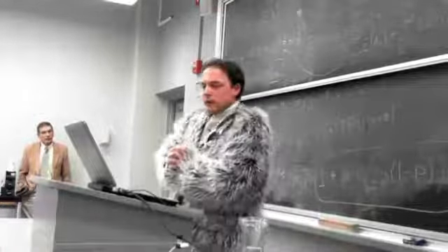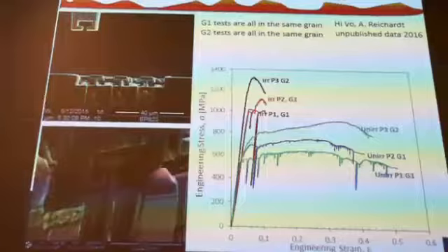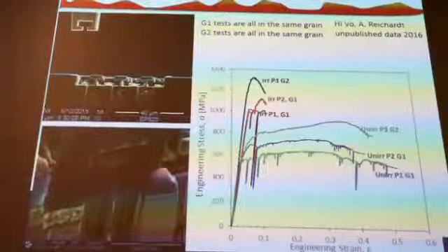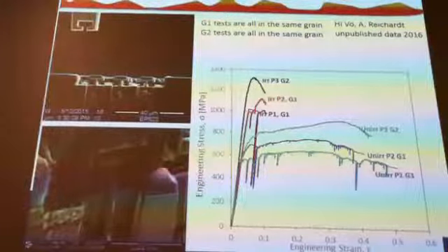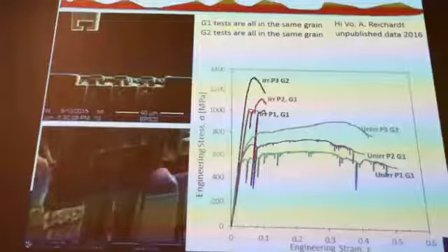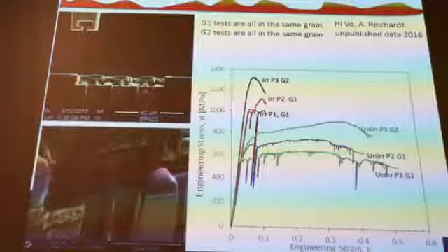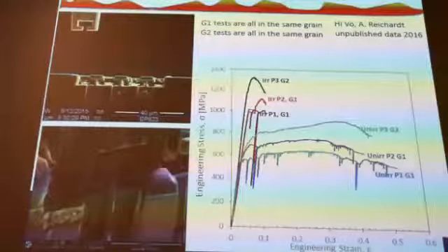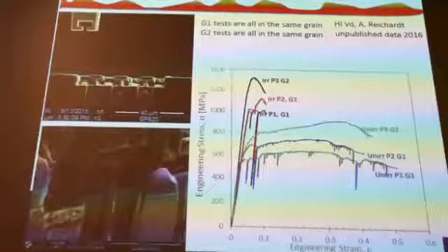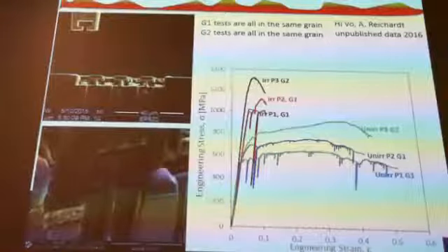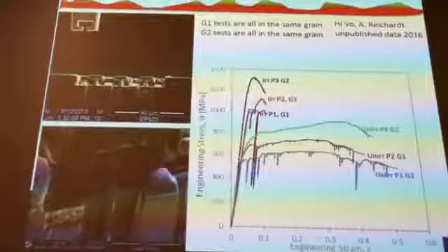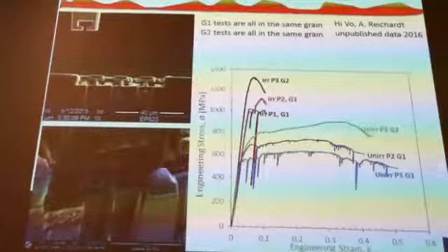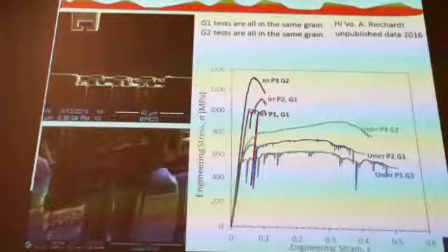What happens is, because the sample is so small, it's essentially a single crystal sample. Once you have a dislocation moving, it moves through the material without much of a hurdle. And as the dislocation moves through it, it suddenly gets longer by that amount, right? But the tool is not fast enough to catch up with the slack in the sudden deformation, so it leads to this load drop. The drop is an artifact of the tool.